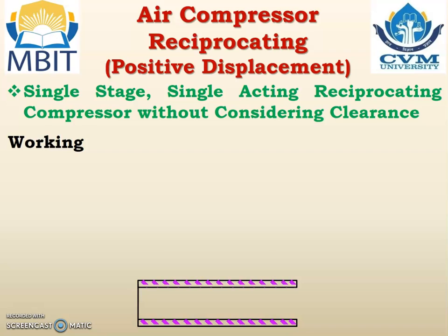Working. This is the cylinder, this is the piston which moves from left hand side to right hand side, and right hand side to left hand side. But it does not reach the cylinder head, so there is some gap, and due to that it is said to be the reciprocating compressor considering clearance.